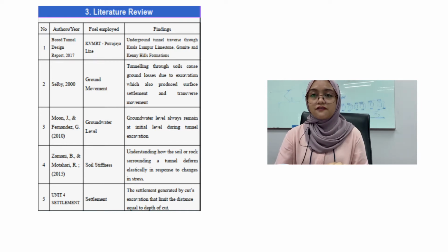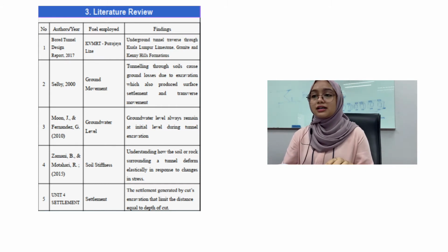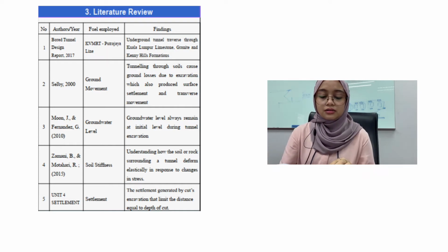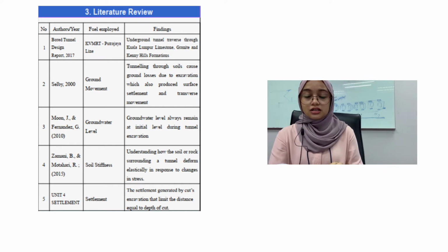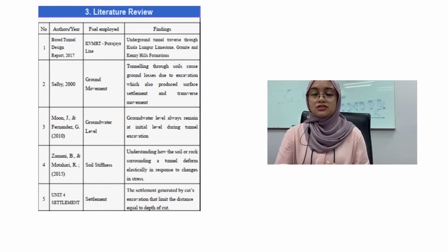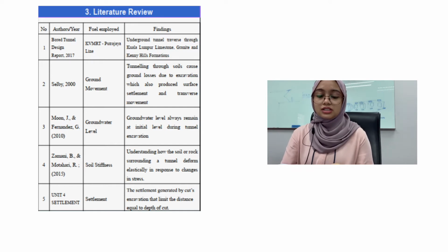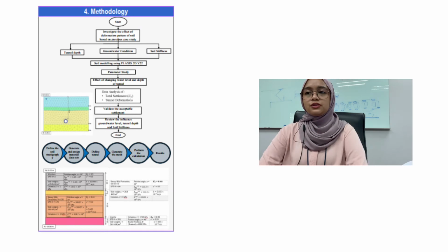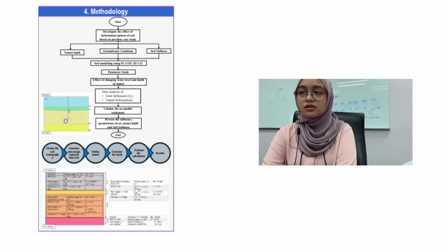In terms of settlement, the settlement generated by cut excavation has a limit distance equal to the depth of the cut. I understand that if a structure is near the excavation project, especially in sandy soil, it will cause damage to the structure and produce more settlement. Next, I will proceed with the methodology of this research.